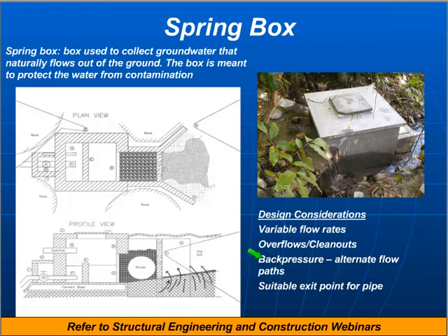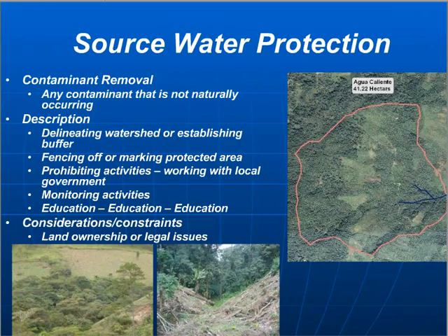And so it's so important to understand that water elevation in the base flow condition or the dry season so that you can make sure that your outflow is not too high. I know I worked on a project where the contractor, when he was constructing the spring box, didn't really follow the design and put the outflow pipe at a slightly higher elevation than what was specified, which caused the water elevation to increase until it could flow out of that pipe. But that created a situation where the water started flowing around the box. And then the flow rate that they needed could not be achieved in that community because the box was no longer capturing all of the water. And so it's really important to understand exactly what that elevation should be of the outflow.